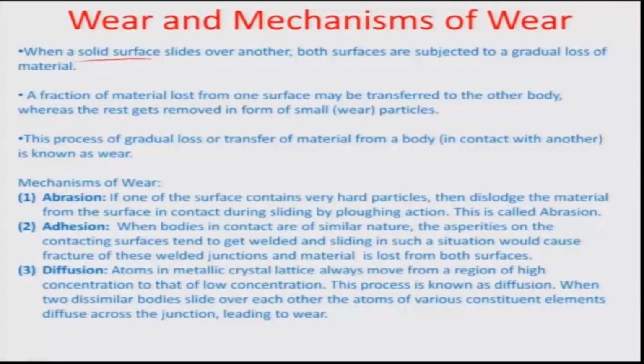Let us look at wear. So, wear is something which happens when a solid slides over another, obviously the surfaces would be subjected to a gradual loss of the material. So, wear is a post friction phenomenon, where when we want to shear the local welds, in the process of doing that, obviously there would be a breakage of the weaker material for the flowing of the top portion or the stronger material over the weaker material.